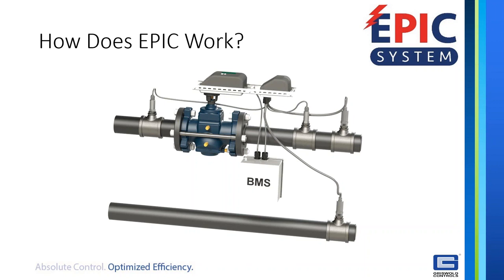So the PI, the pressure independent valve, maintains the correct flow, obviously, in spite of pressure changes. And that's one thing that our unit does that other competitors on the market that are not pressure independent don't. So that way you're only getting a flow change when there's a demand change or when the delta T is outside of the specification. So the EPIC controls the valve based on the delta T. The temperature sensors are measuring the delta T across the coil. So the EPIC controller, the brain, which is shown in this box behind the MVP, knows to open or close the valve based on the delta T requirements, right?